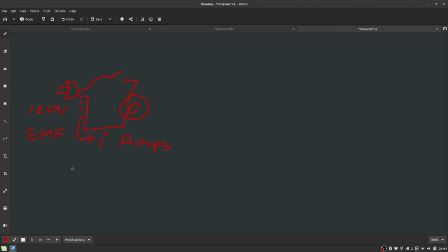And if I do my math right, and it turns out if I say voltage, which for whatever reason in electrical is E, sometimes it's also V, times the current, I end up with the amount of power that this circuit uses. And power is in units of watts. Watt? No, sorry, bad joke. You may slightly be familiar with watts. For example, you can buy, let's say, an 800 watt power supply for a computer, or back when incandescent bulbs were a thing, you'd have a 100-watt light bulb. That basically says how much power is being used by this light bulb. And it turns out to be just the amount of volts times the amount of amps.